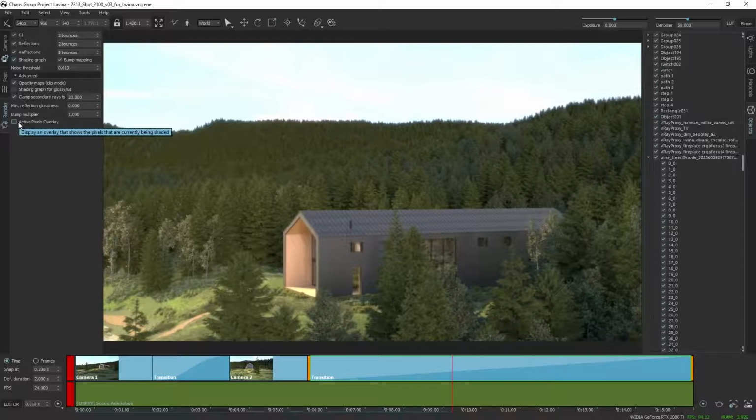And by the way, with this you can see the frame rate is becoming higher and higher because fewer and fewer pixels are being sampled by Lavina. This is actually a quality and speed setting that you can use, and it works on the static frame currently, and also with the high frame rate sequence rendering as well. So make sure that you use this one when you're doing these renders.